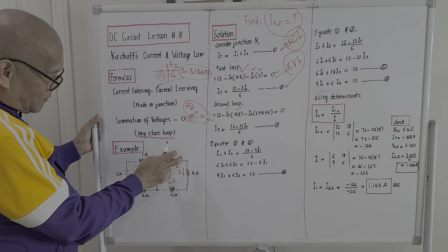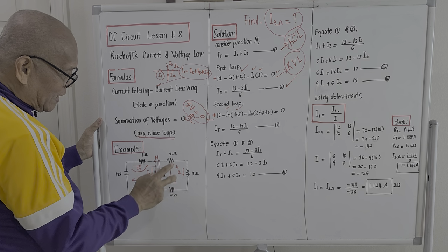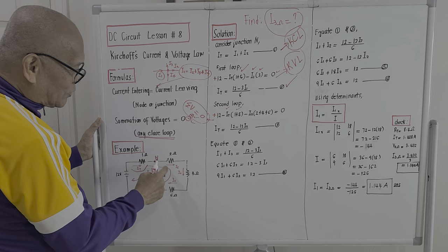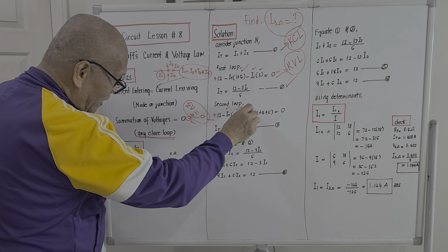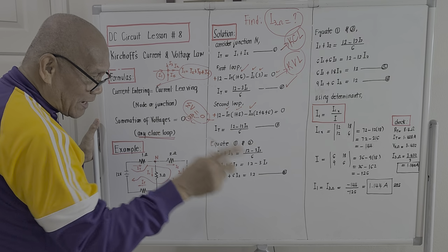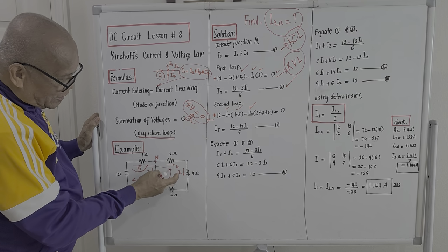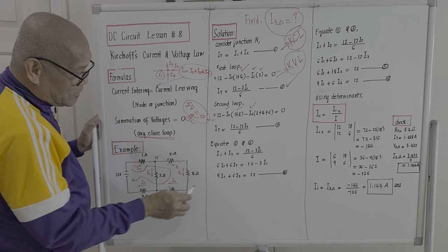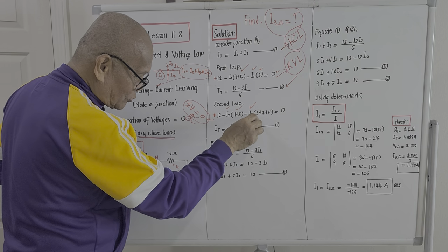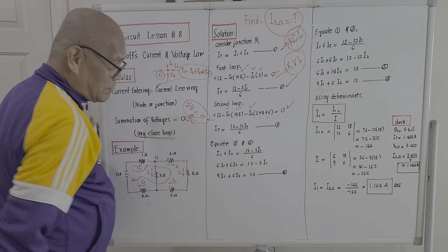And the voltage drop across this one, plus this one, plus this one, the current passing through them is I sub 2, it's common. So the unknown current I sub 2 is multiplied by the 3 resistances through which it passes: the 2 ohm, 4 ohm, and 6 ohm. So this is multiplied by the quantity 2 plus 4 plus 6, and this should be equal to 0.